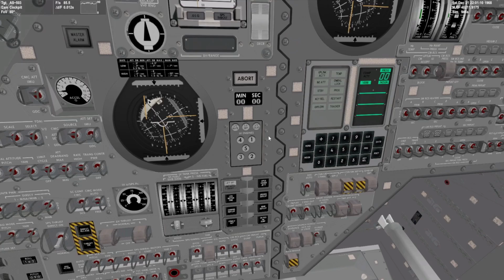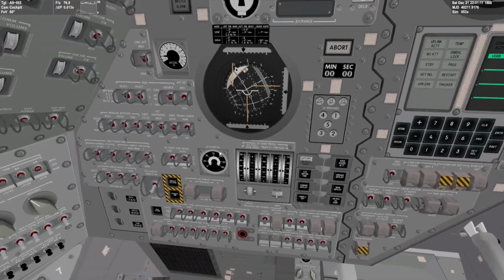But if you are going to be doing other things in the spacecraft and you want to be totally sure it's not going to drift out and you don't plan on time warping, then leave it in SCS with the BMAGs caged. That will keep you in, I believe, a 4 or 5 degree window of error before it kicks the thrusters back. So very minimal fuel usage.